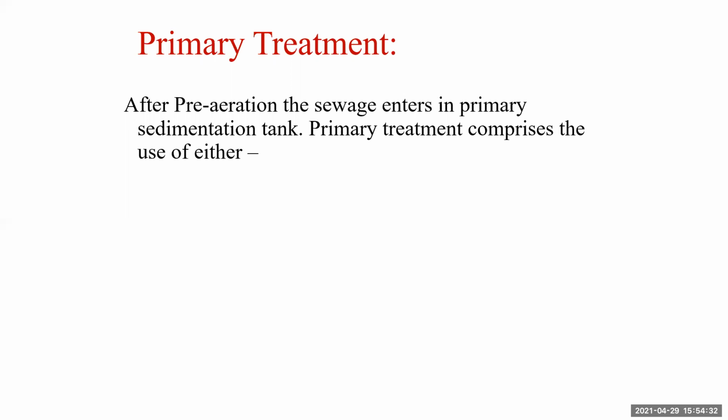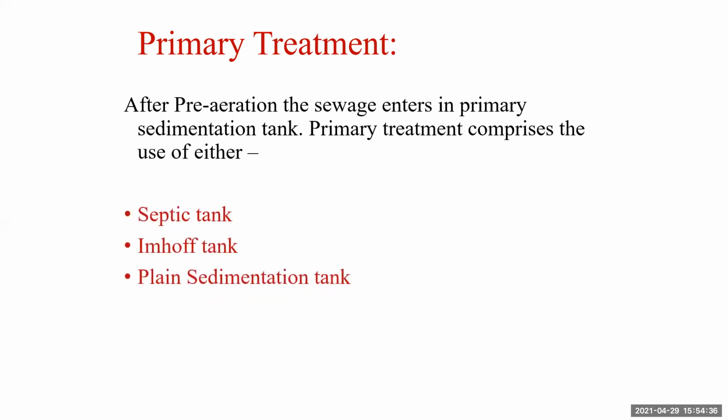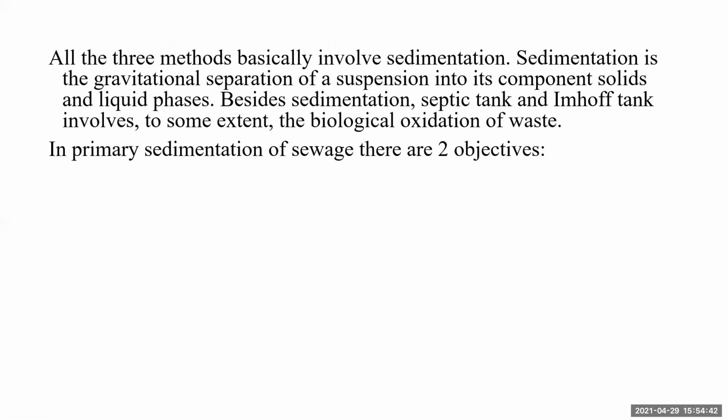Now the primary treatment given in the primary sedimentation tank comprises using a septic tank, an Imhoff tank, or a plain sedimentation tank. All three methods basically involve sedimentation.